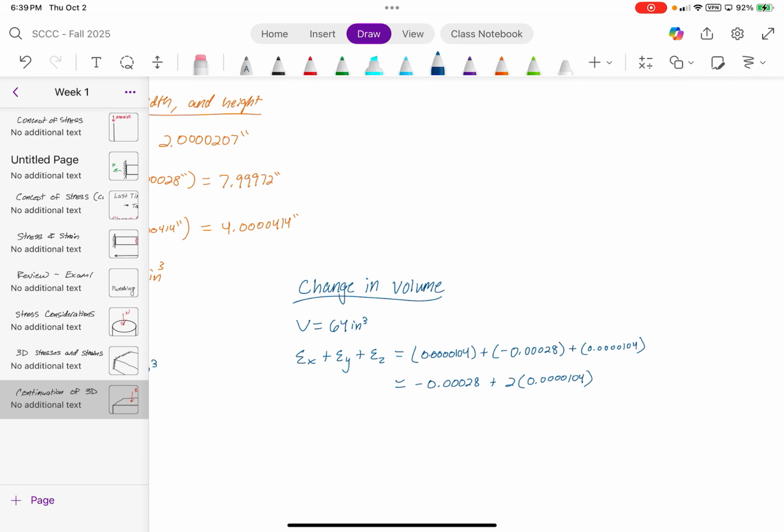The approach would generally be the same, but you would need to consider some variation in the stiffness. You would really need to determine what the forces are in each composite, which we will learn about next week. Then you would treat each material as a separate material, with the condition that now there's a boundary separating the two, which generates stress. In a lot of cases with composites, the material is so strong that you're not really worrying about that volumetric change.